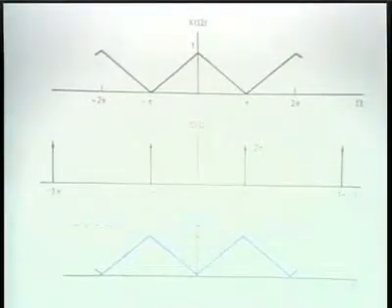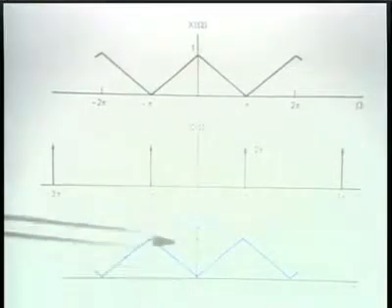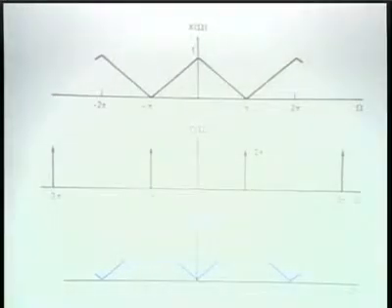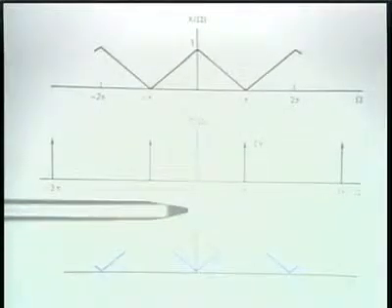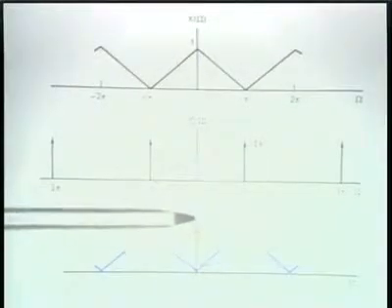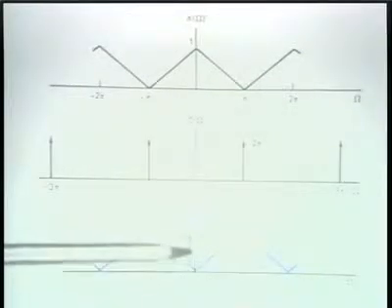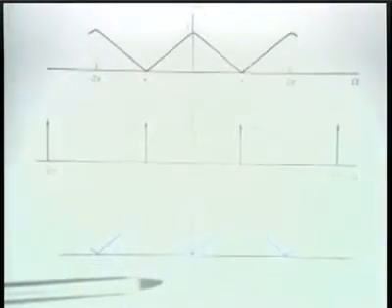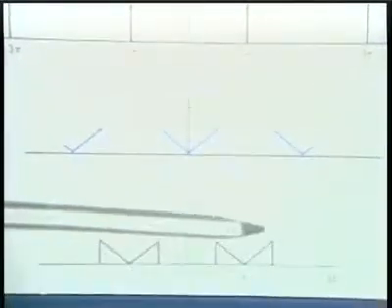and what happened at high frequencies now happens at low frequencies. Well, if that's processed now with a low-pass filter, and this dashed line indicates the low-pass filter, then the result that we get is shown here, where we've extracted the low-frequency portion of the modulated signal. And now when we modulate or demodulate back, then this spectrum is shifted back to where it belongs. Namely, it's shifted back to be centered around minus pi and around plus pi.